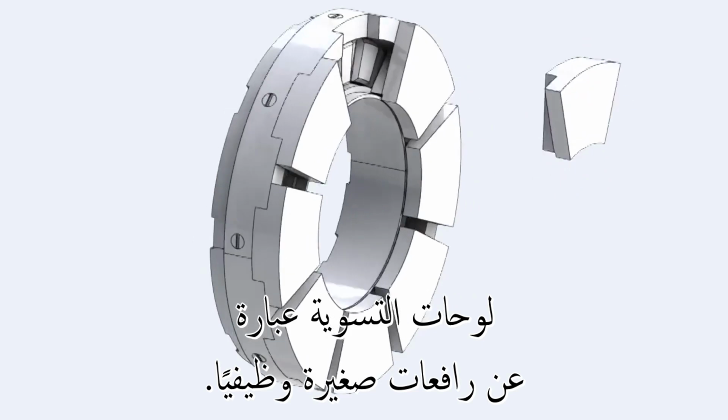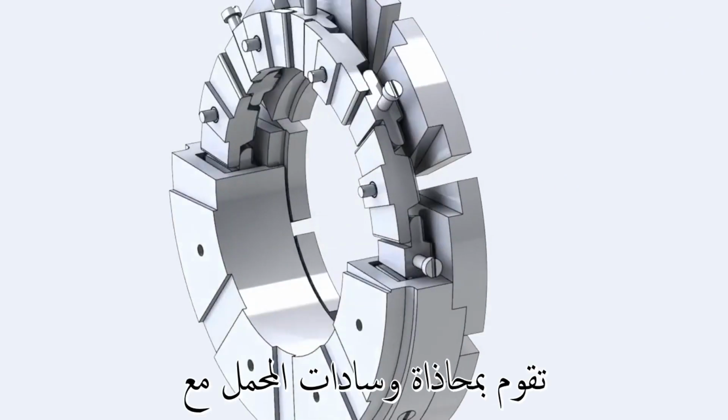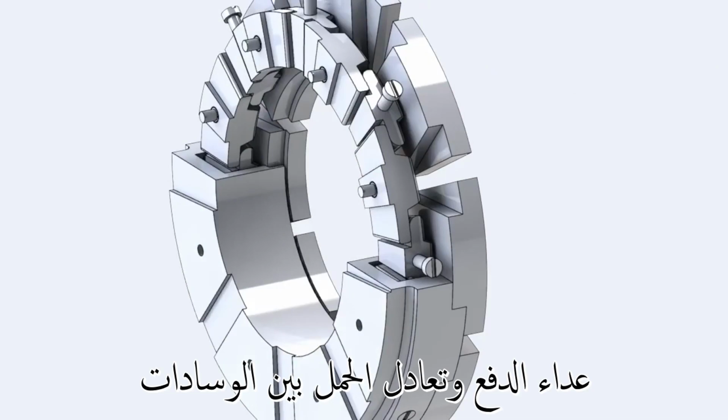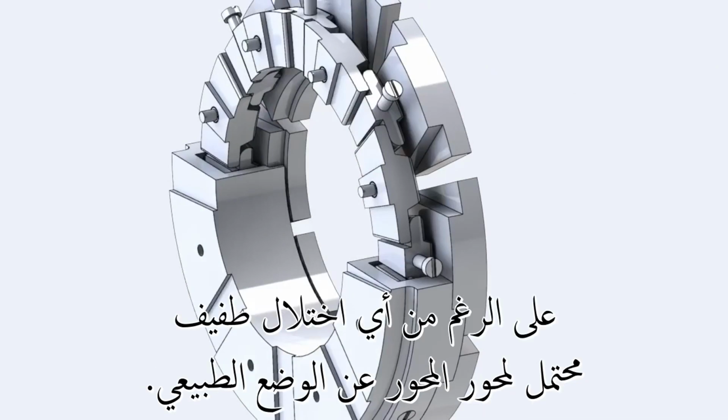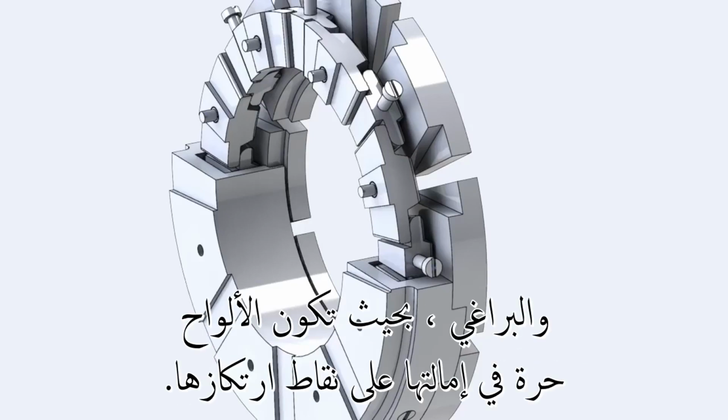The leveling plates are functionally small levers. They align the bearing pads with the thrust runner and equalize the load among the pads despite any possible slight misalignment of the shaft axis from the normal. The leveling plates are mounted on the base ring by dowels and screws such that the plates are free to tilt on their fulcrums.